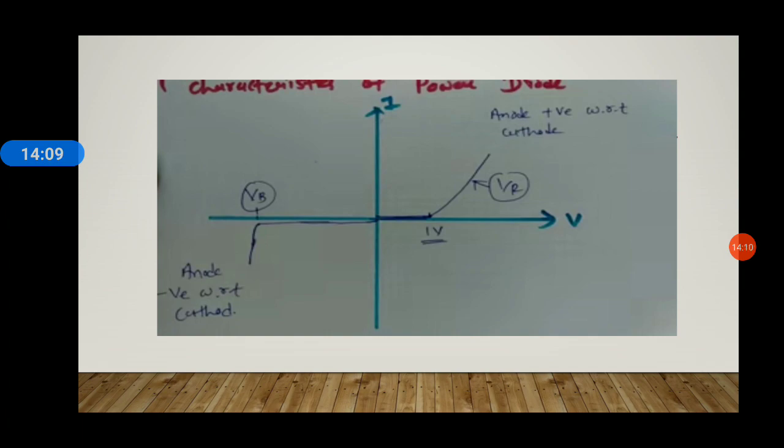Now this is the IV characteristics of a power diode. As mentioned before, it is the same as the normal, conventional PN junction diode. A diode conducts when the anode voltage is higher than the cathode voltage. The forward voltage drop across the diode is very low, around 0.5 volts to 1.2 volts, approximately say 1 volt.